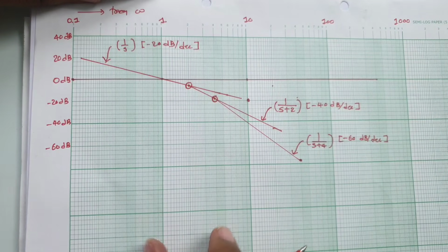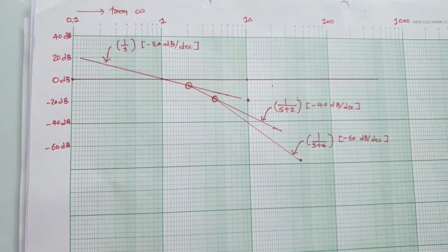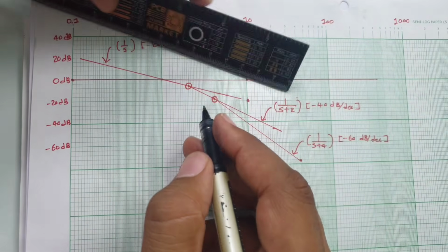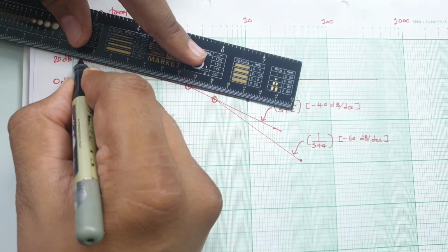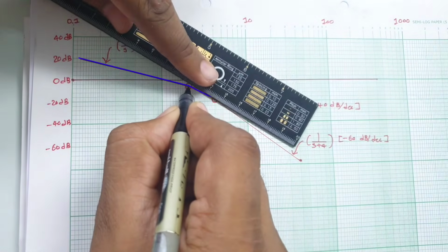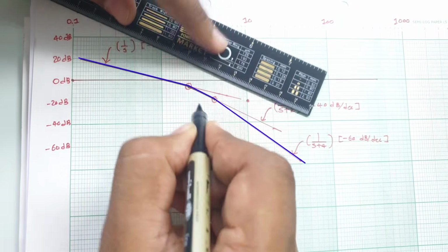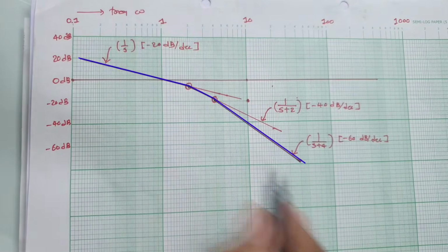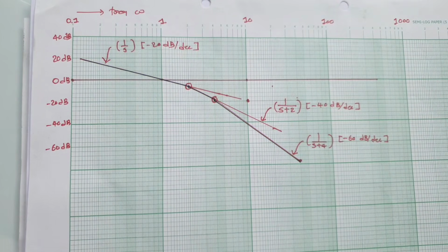So this is how we can have a gain plotting, right? And in this, let me tell you, the actual gain plot is corner frequency to corner frequency only. So that is this. These are just extensions, right? You see, so this is our actual gain plot that one should know.